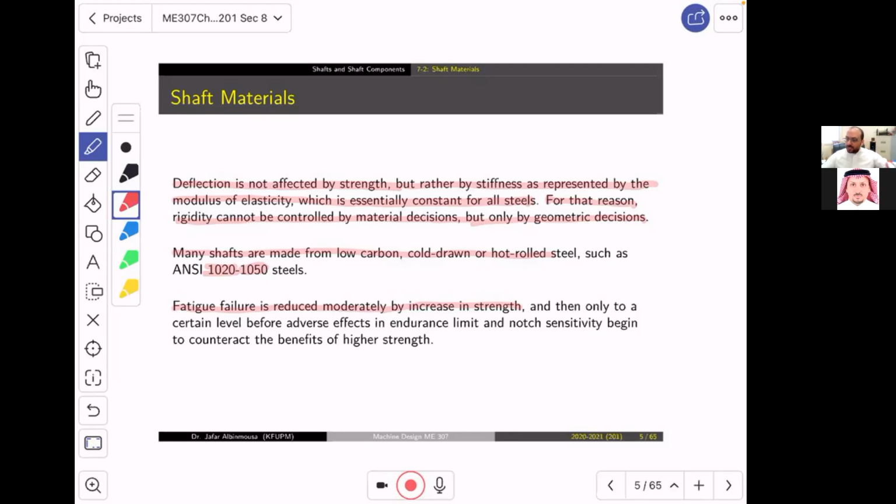Actually, crack turns out to be like, if you have plasticity, it makes the crack go like in mud, so it slows it down. Of course, this is not as simple as this. There are too many details in there, but this is the general idea: you don't necessarily need to push for higher strength in order to get better performance.